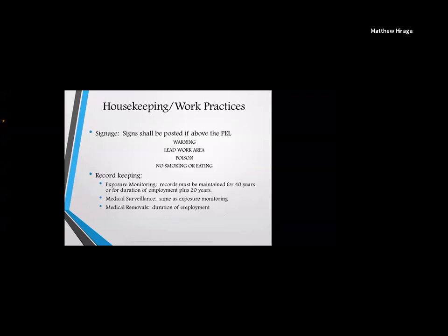So housekeeping, your signage: the sign needs to be posted anywhere you're going to be above the PEL at any point. It'll read something like warning, lead work area, poison, no smoking or eating, authorized personnel, caution, keep out, right?